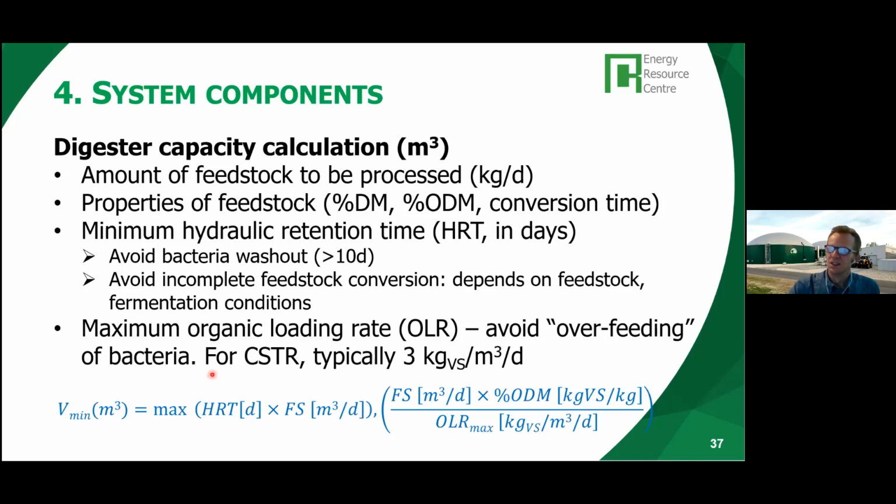Now, for let's say general digesters, let's say stirred and heated digesters, you might get typical organic loading rates of up to about 3 kilograms of volatile solids, let's say organic dry matter, per cubic meter per day, and it can be higher than this for highly optimized systems, but this maximum loading rate of 3 is quite a typical high range value.